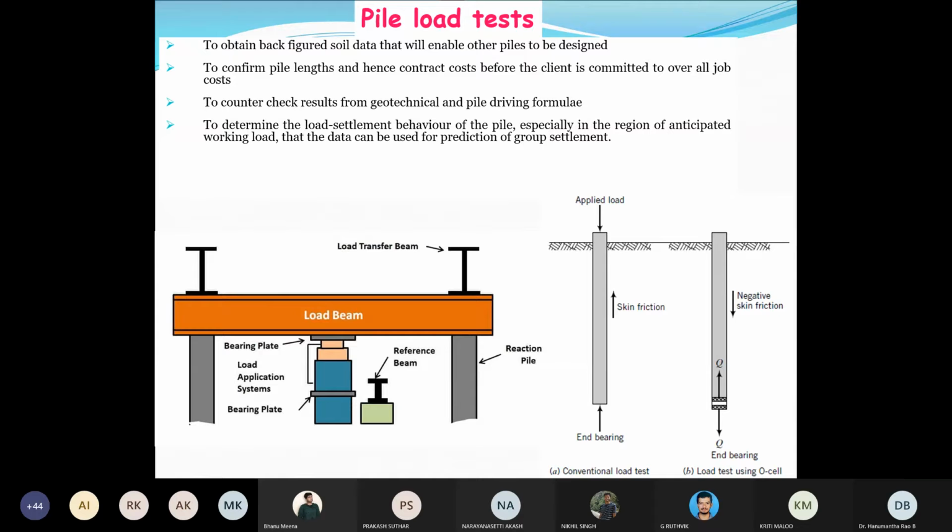That means soil may fail prior to the pile or concrete, and vice versa. Therefore, another primary objective of the pile load test is to establish load versus settlement, then to verify the structural soundness of the pile.